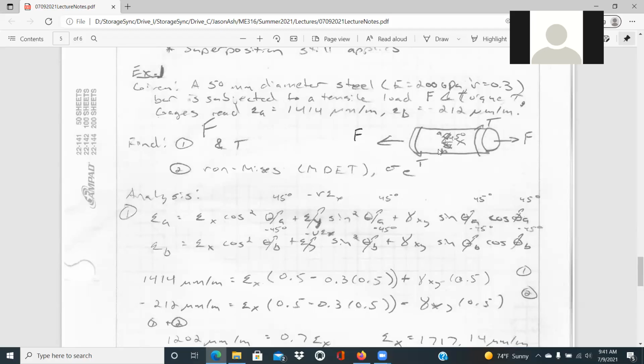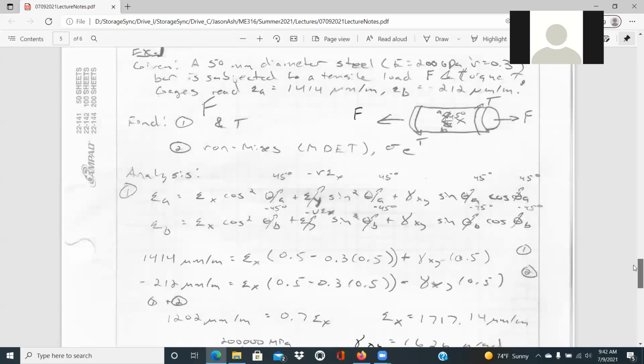I assisted the formula team one time in looking at a torsion bar to transfer loading at the rear wheels. And we put a strain rosette on there so that we could measure the torque with strain gauges. And so it has that same concept.